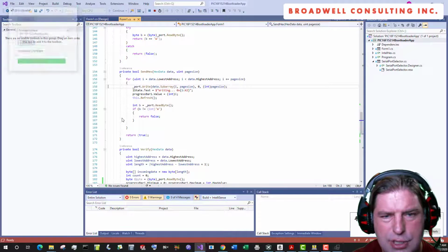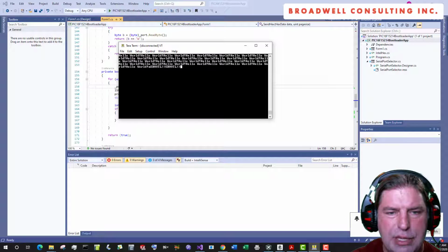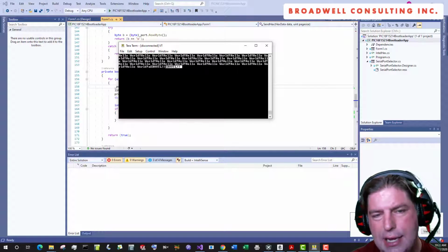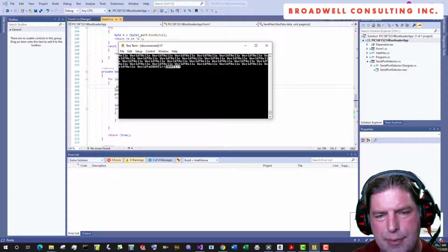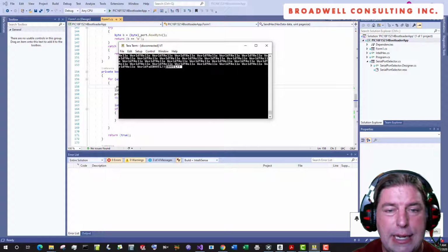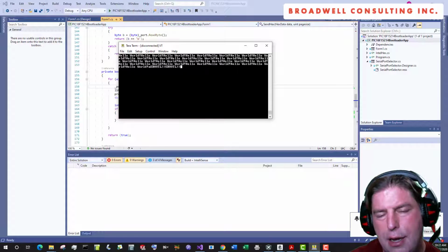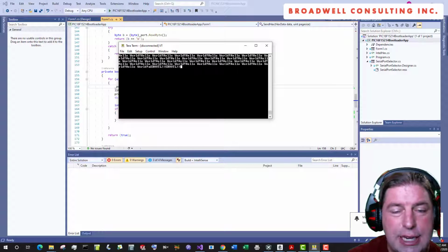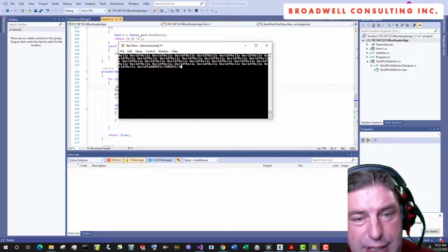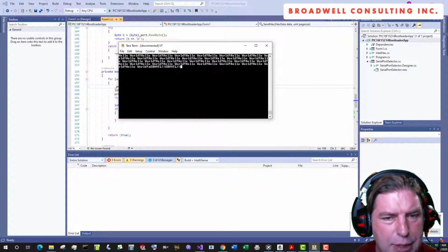Now at this point, we'll close that. And we can see when we went into boot, it said eboot L. That's actually to work with what looks like a command from another application that I'm working on. You could make it say whatever you wanted. But it said eboot, and the L indicates that the low byte of the magic word did not show programmed, so the bootloader decided to stay in the bootloader, which it should. Now at this point, we have a loaded application.